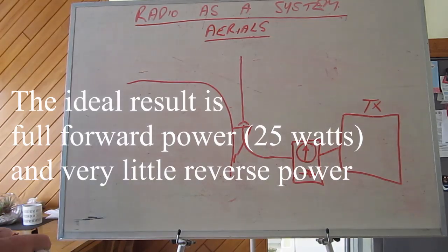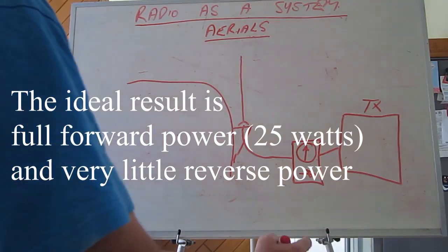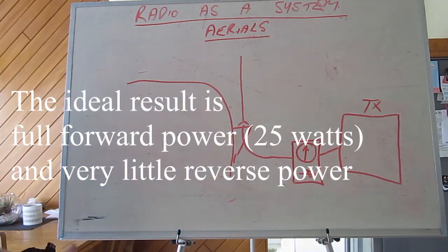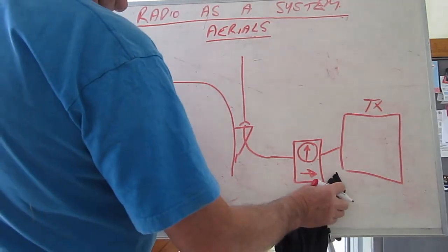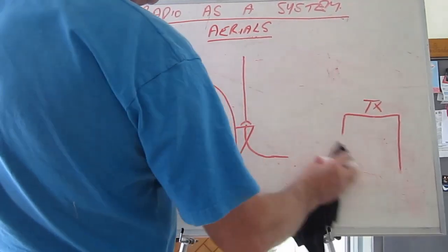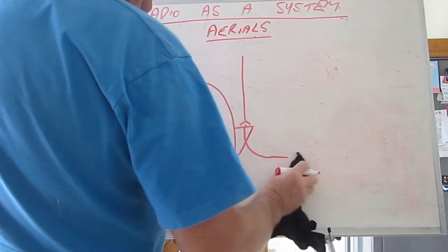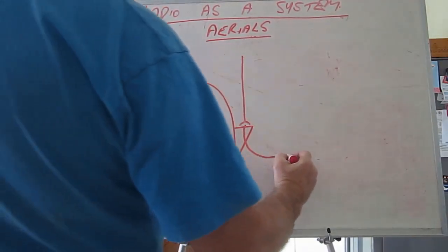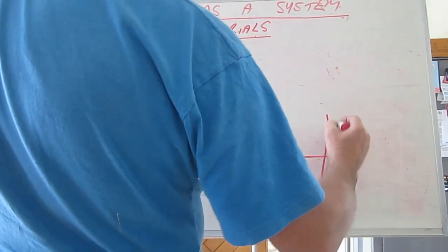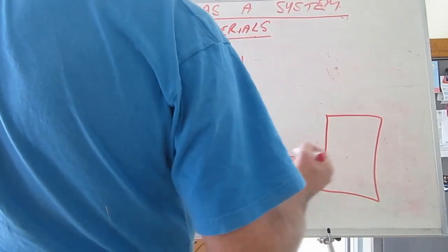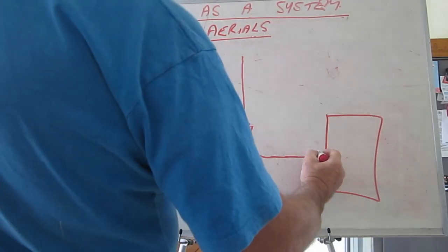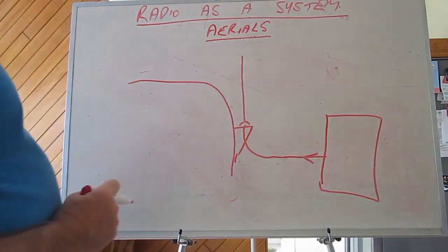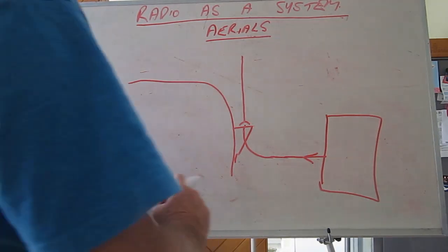There's another way of actually dealing with this issue, and that doesn't involve a transmitter at all or a VSWR meter. What you can do is sweep this with an instrument. I have an Anritsu Sightmaster, which is very valuable from this perspective. And the Anritsu Sightmaster will give you a graphical indication